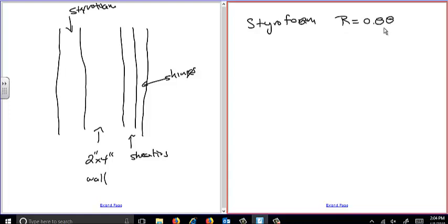Now these don't correspond to the R values that we did in class, because those were English units. These are SI units, and the units are meter squared, degrees C, seconds per joule. The R values, like an R value 6, are feet squared, degree Fahrenheit, seconds per BTU or something like that. So don't worry if those don't look like something you've seen before. Then I see something that says 3.5 inch fiberglass batting.